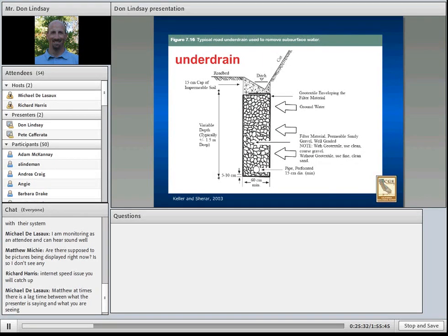There are two common types of subdrains. The first is an underdrain. Common underdrains are constructed to intercept shallow groundwater flow and direct it beneath the road surface through a pipe. An underdrain typically consists of filter fabric that is wrapped around coarse drain rock with a perforated pipe placed at the bottom. It is possible to eliminate the use of filter fabric if using a properly selected graded drain rock, since the graded drain rock will form a natural filter bridge. Choosing the correct gradation of drain rock, however, does require laboratory testing and experience.